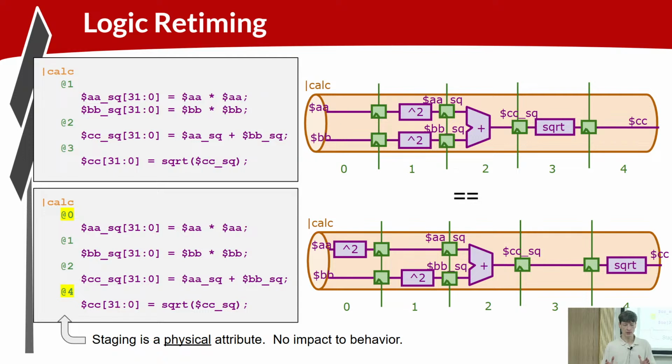Yeah, so the flip-flops are going to exist wherever they're needed, right? So the existence of these flip-flops, the existence of stage 0, just depends on the assignment of A and B. Where are their assignments? Right, so the pipelines are conceptually infinite. All signals exist anywhere they're needed. So my showing flip-flops implies that I've implemented this. The implementation and the existence of those flip-flops just depends on the surrounding logic.